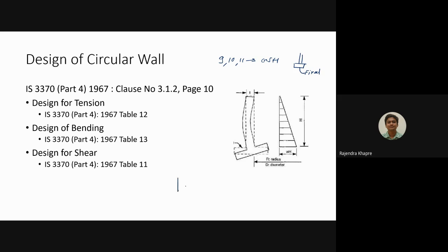Why is this so? Because if you see, the GSR looks like this. There is a complete solid slab which is supporting this vertical wall, isn't it? So this is a continuous one. But as far as the foundation of this part is concerned, it is not continuous, right? It is going in a circular fashion, but then we have a slab over here, then we have a wall over here, something like this. So some rotation is possible over here, whereas in GSR the rotation is not at all possible. So this is a different condition where the rotation is possible in the foundation.